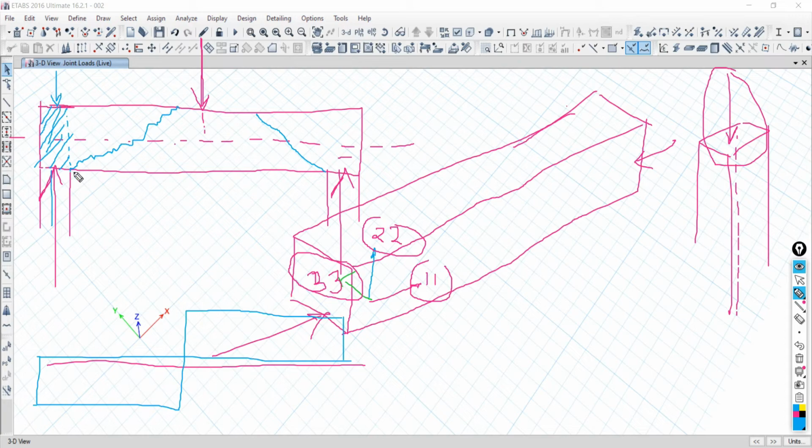It is stiff and stable enough. But this is the cantilever part and the load is coming. So over this joint it is lacking its strength, and due to heavy stress and sudden loss of contact surface, there is the possibility of development of a crack, and that crack will propagate along the depth of the beam.